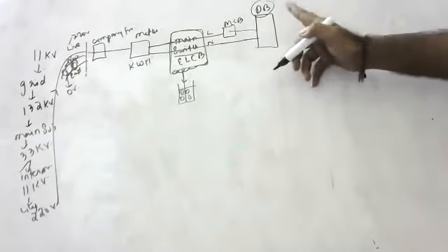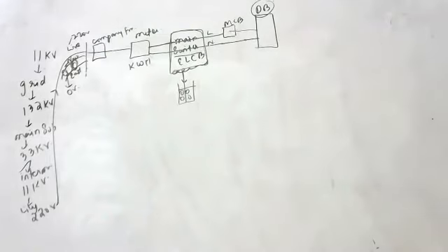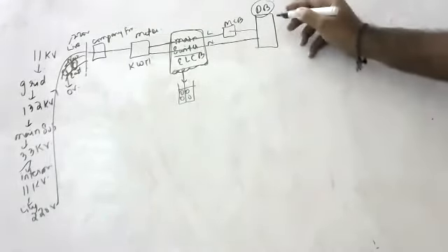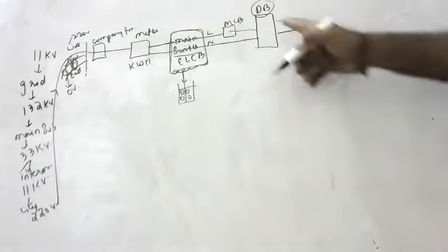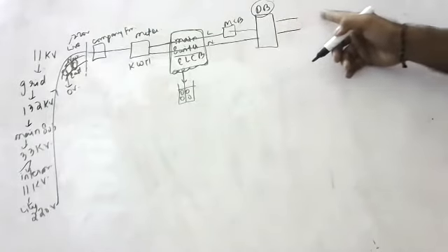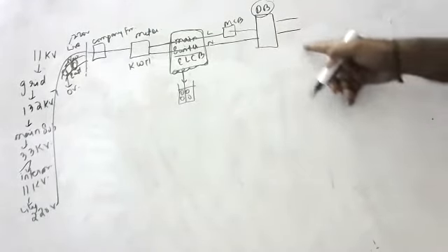Children, ring system. In this system, we have separate rings for each portion of the house. Separate rings will be coming from each portion of the house. One ring I will show. Wires will start from the distribution box, run around all the rooms of that portion, and come back. Imagine one portion I'm showing, children.